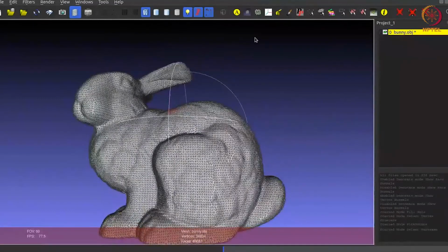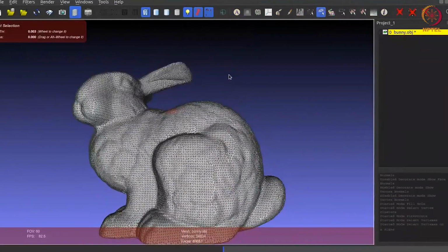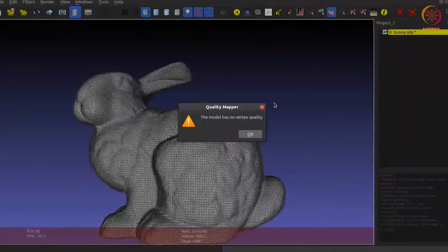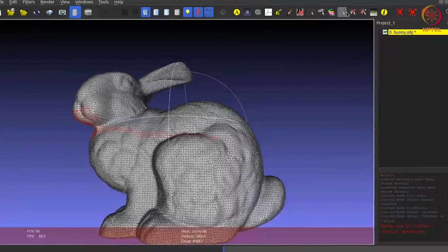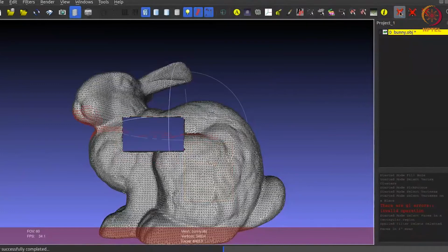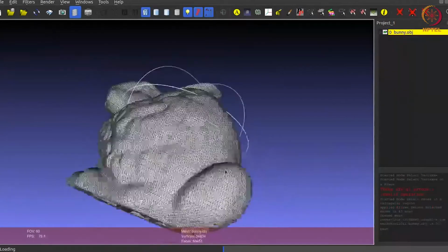I would advise you to explore it even more. You can directly select points belonging to a particular plane. Similarly, you can even delete a set of vertices, and you can select a set of faces. Essentially, I can directly pick some set of faces that are lying in this particular region and even delete them. All these operations are pretty quick with MeshLab.